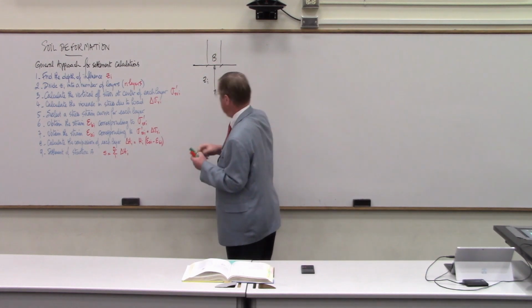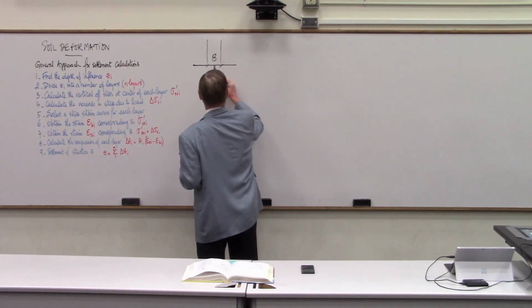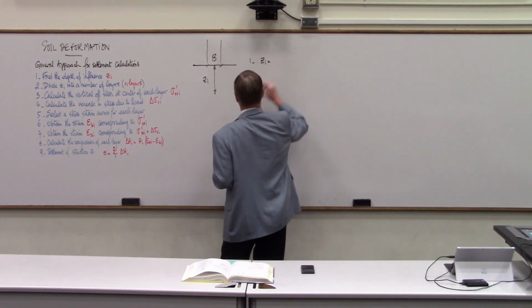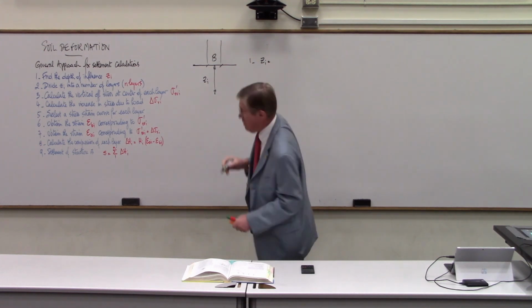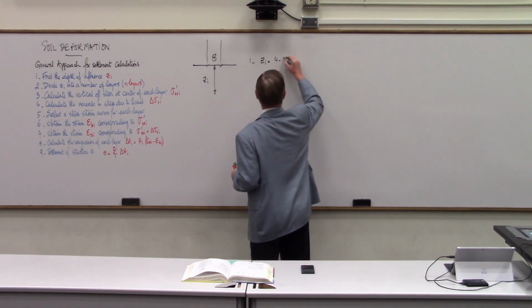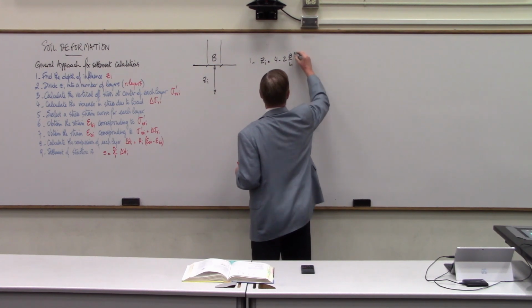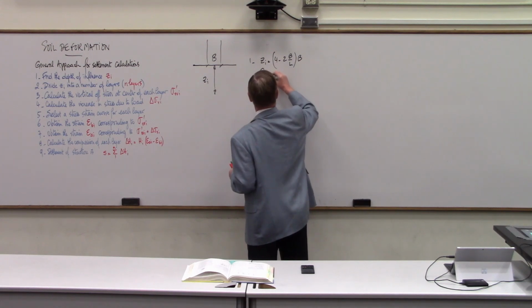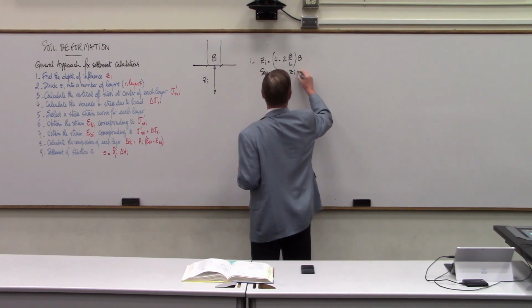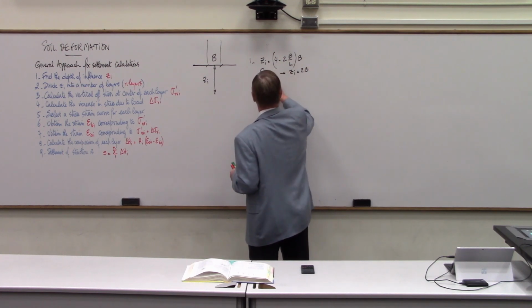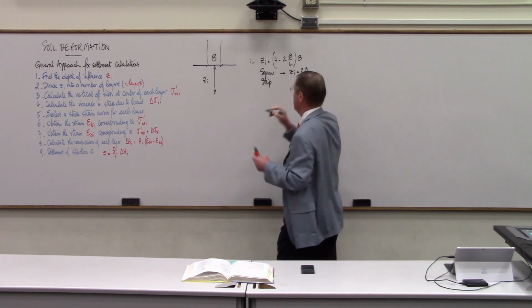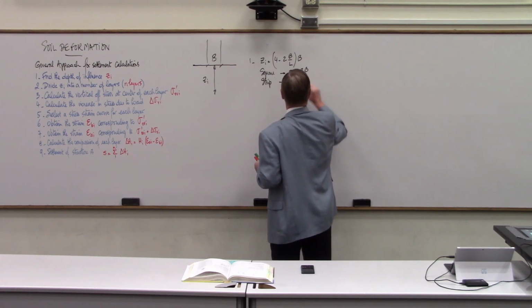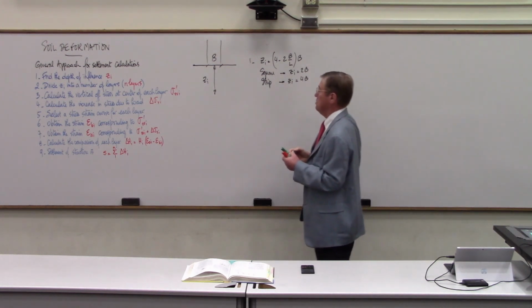So this is step one. We said yesterday that ZI is equal to (4 minus 2B over L) times B. So that if I have a square foundation, then ZI is equal to 2B. And if I have a strip foundation, a very long one, then ZI is going to be equal to 4B. Right? So that's the zone of influence.